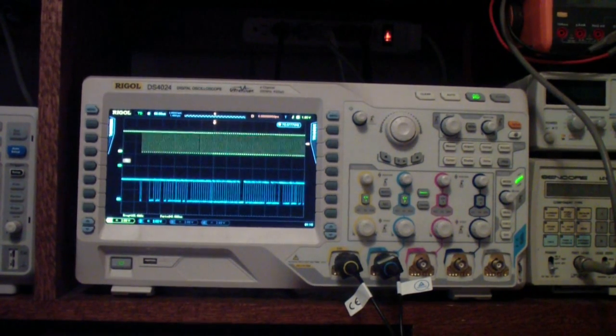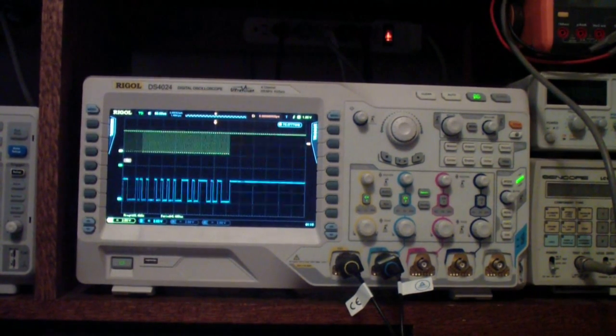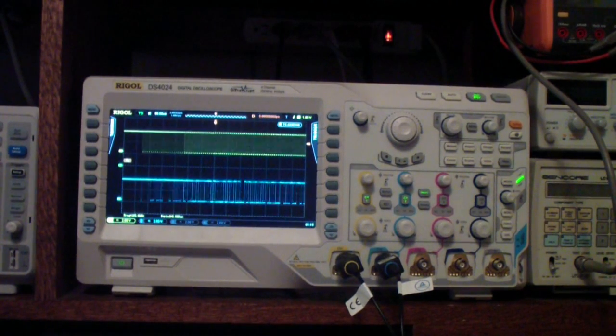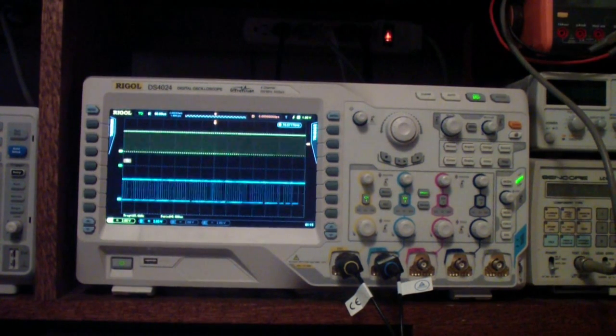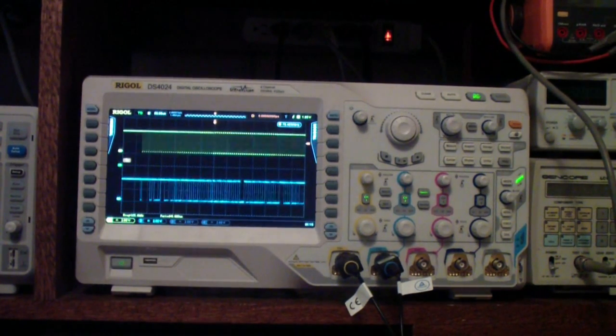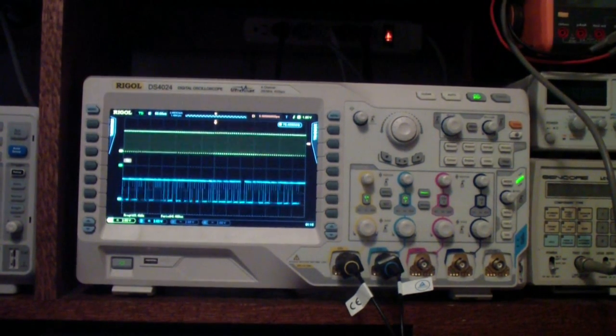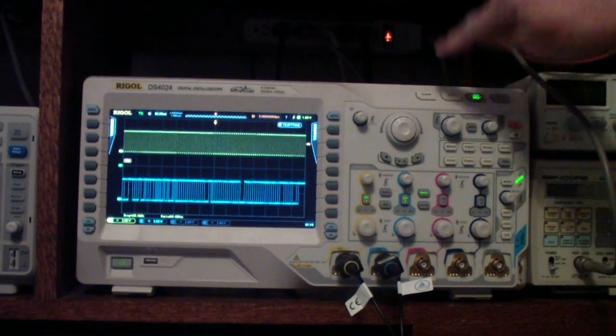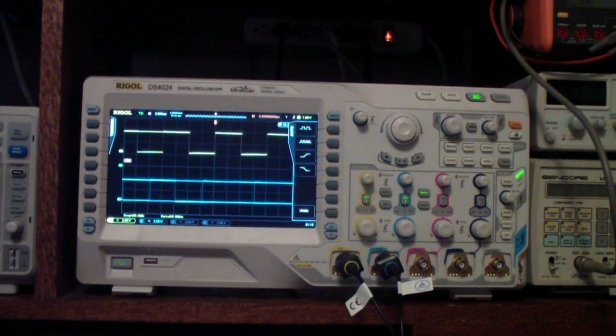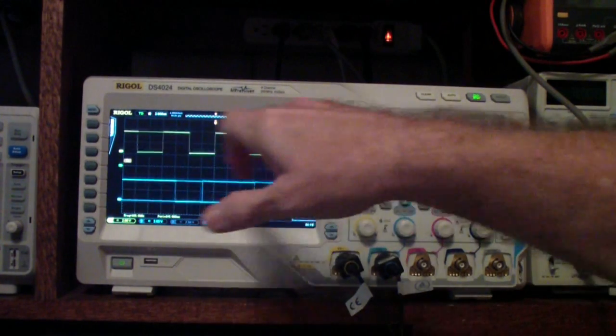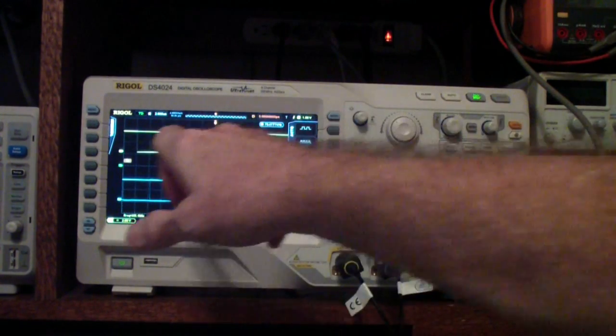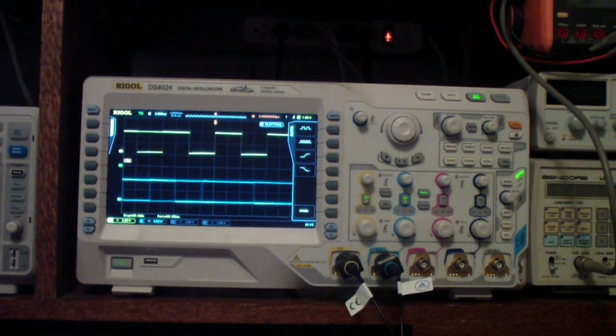Now what I'm going to do on this one is walk you through the process of doing this. It is exactly the same on this scope as it is on the Rigol DS1000, and the setup is basically 3 steps. The first step is to get the scope into a mode where you can set up the trigger and decode, and all that involves is pressing the auto key. That will get the trigger levels set approximately right for, in this case, channel 1.